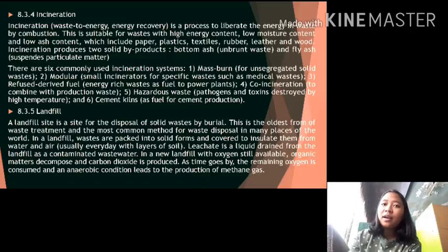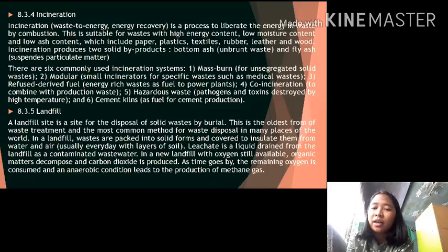8.3.5 Landfill. A landfill site is a site for the disposal of solid waste by burial. This is the oldest form of waste treatment and the most common method for waste disposal in many places of the world. In a landfill, waste is packaged into solid form and covered to insulate it from water and air, usually every day with layers of soil. Leachate is a liquid drained from the landfill as a contaminated wastewater. In a new landfill with oxygen still available, organic matter decomposes and carbon dioxide is produced. As time goes by, the remaining oxygen is consumed, and an anaerobic condition leads to the production of methane gas.